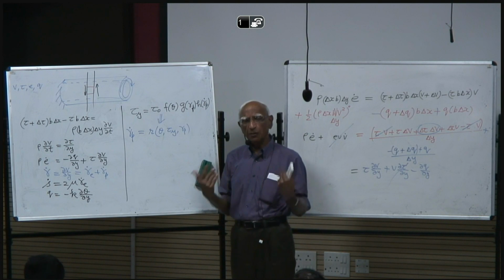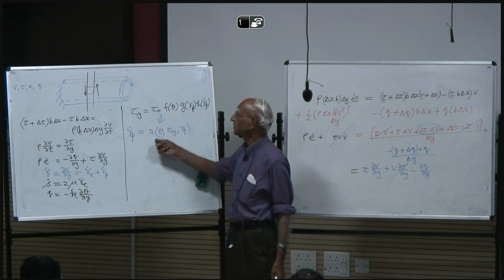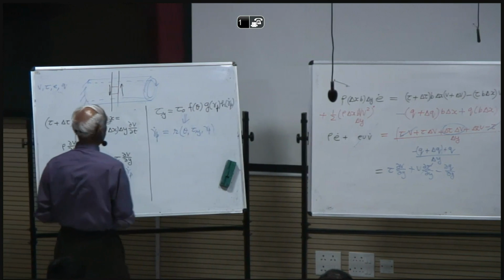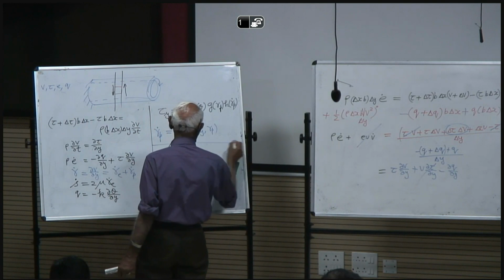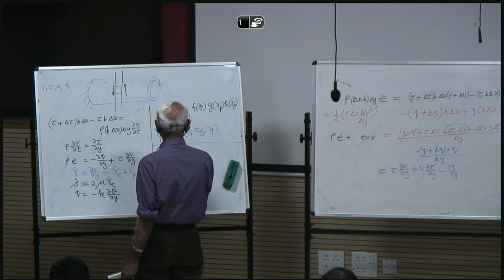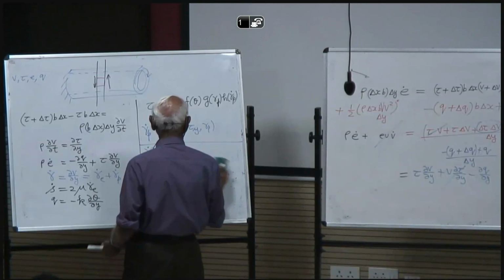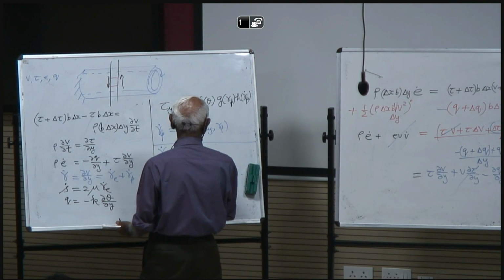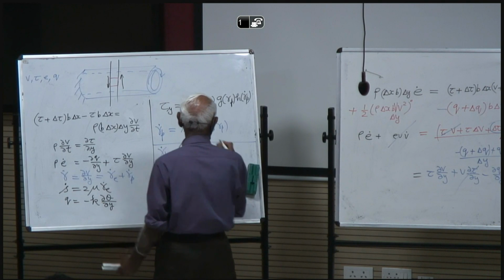If my stress equals the yield stress, I will solve this equation for the plastic strain rate. So my equation here then becomes gamma p dot is equal to the maximum of 0 or this value.